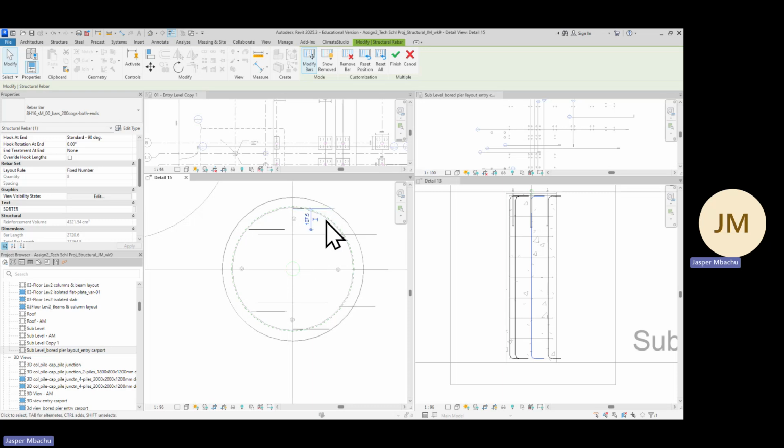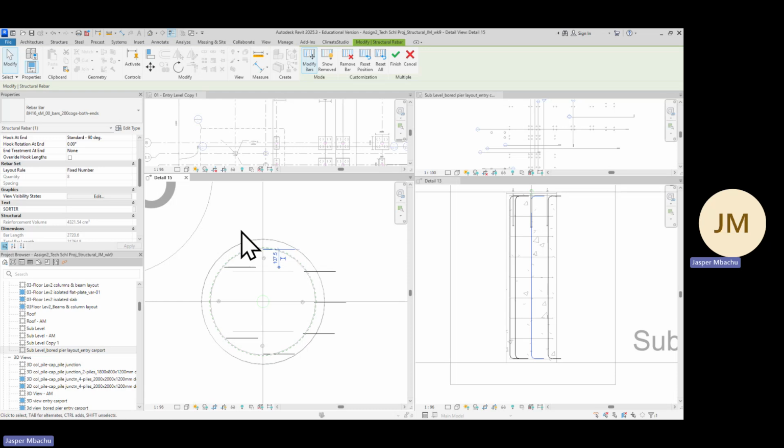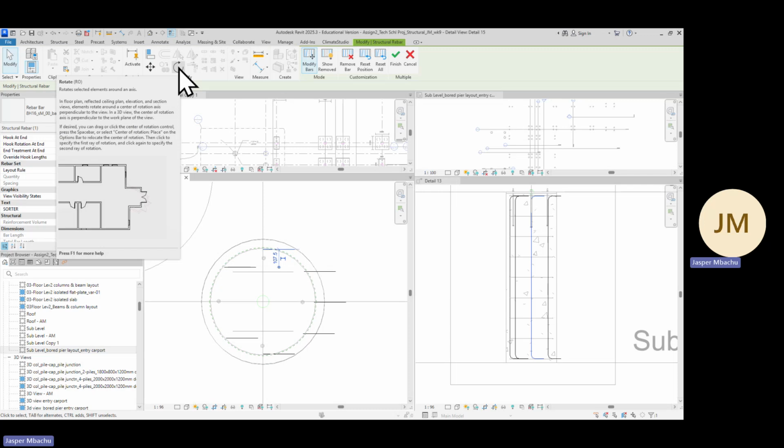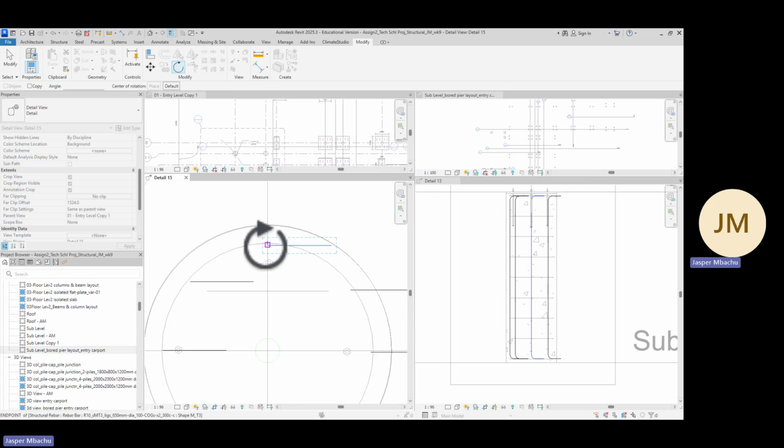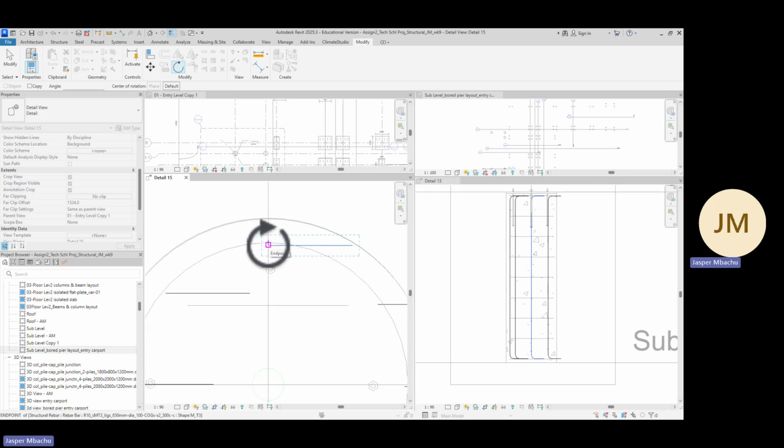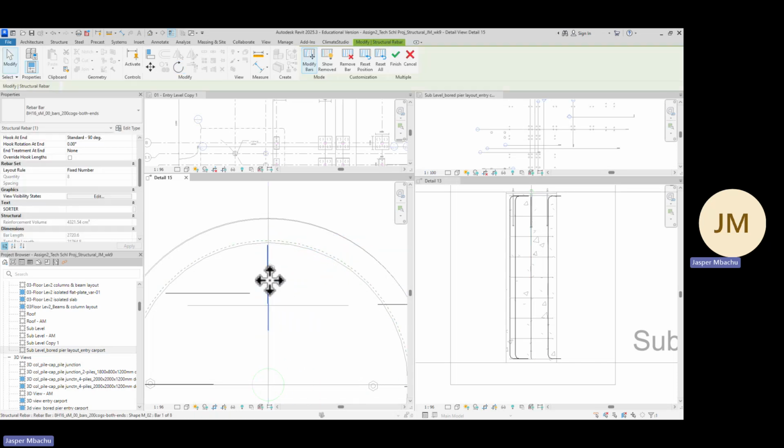When you select one instance of this bar, maybe I selected the top one, I'll use the rotation. Can you see this rotate? When you click on rotate the bars, the default rotation is the middle point, but we don't want to rotate from this side. Can you click on your bar spacing? Click on bar spacing, then it will ask you where you want to rotate from. So you position at the base. Click on the base, and then follow the line where it was pointing before, and then start rotating to where you want to position it, which should be 90 degrees, or just bring it vertically, drop it.